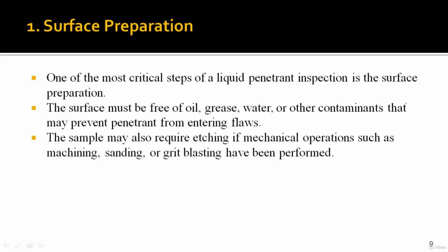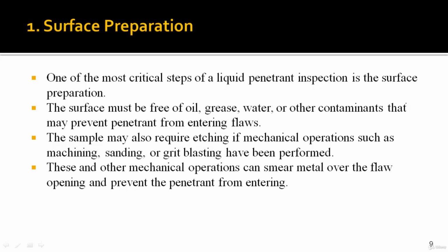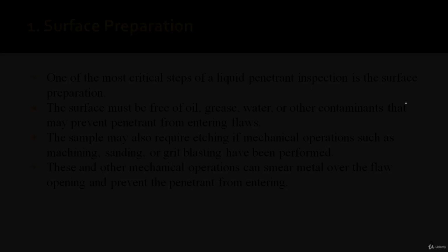The sample may also require etching if mechanical operations such as machining, sanding, or grit blasting have been performed. If some operation is performed, it may be possible that there will be some scratches also. So we have to do etching using some etching agent, so it will be clean. These and other mechanical operations can smear metal over the flaw opening and prevent the penetrant from entering. If there are impurities present there, then what will happen? It will block the penetrant from entering the voids, and the operation will fail.